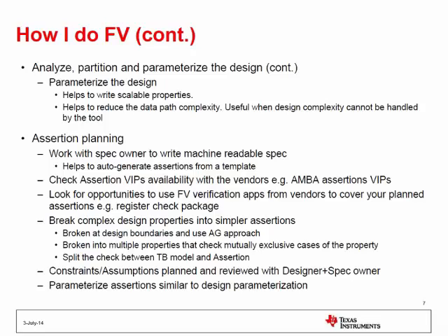There are a couple of things I said: you can break it at design boundaries, or break it into multiple mutually exclusive properties, or you can do a split. If you're trying to write a property which is complex, for example, one of the gentlemen asked, how do I do a protocol verification? If you're trying to write a complete property for a protocol, it becomes very difficult. What you can do is build a very simple model which actually implements the protocol, and you can write an assertion on top of the model.